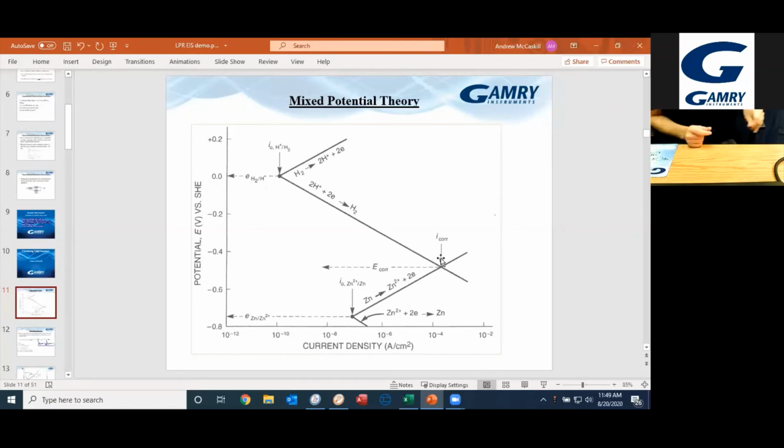And you can look up information on how you use the mixed potential theory on any number of different constituents that are in the material, but be wary of that. I think I talked about it with the PolRes demonstration, but whatever corrosion rate you come up with, it's a mixture of all those different materials, or one of those materials is absolutely dominating the rest. So be wary of that stuff. I think I kind of went off on a tangent with the question, but still just thinking about helpful things that people can consider when doing this.